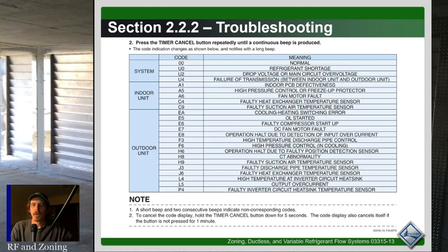So, refrigerant leaks, especially because the line sets are small, can be hard to detect if you don't have a nice long test on them. So it's kind of important to make sure you do your due diligence on testing and vacuuming the system properly. But yeah, most of your troubleshooting is going to be learning how to retrieve a code, learning how to determine what that code is telling you, and learning how to troubleshoot that code.